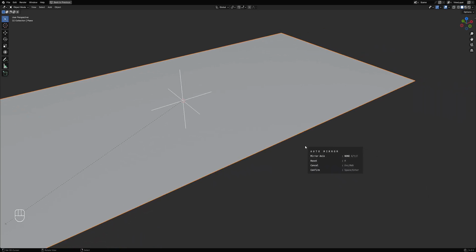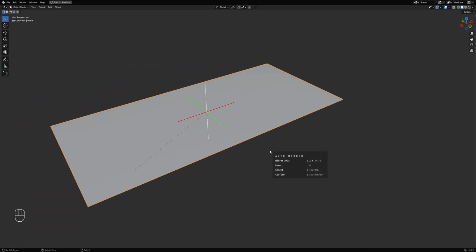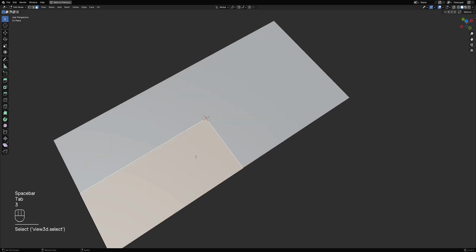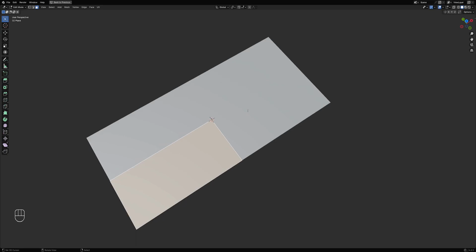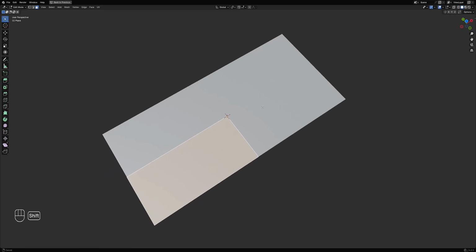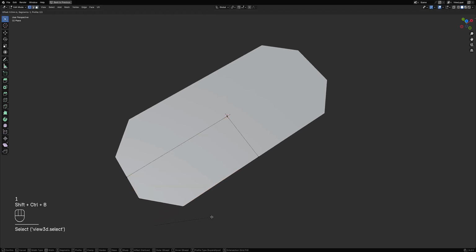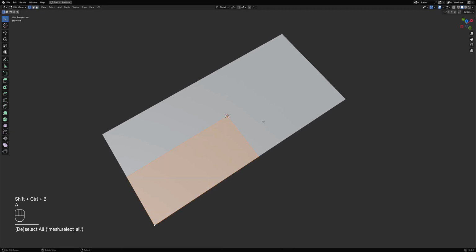If you activate, for example, X, then that axis will color up or light up. Then Y. So we only need to mirror this in the XY axis, and then you can press space or enter to activate. You can see that the area that we click is our real geometry, and the rest will be the virtual mesh generated by the mirror modifier. And now we can do symmetrical modeling.